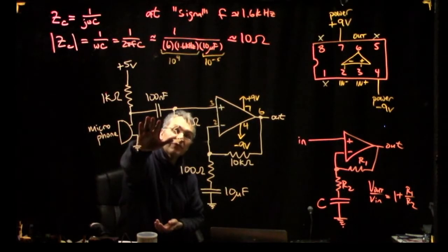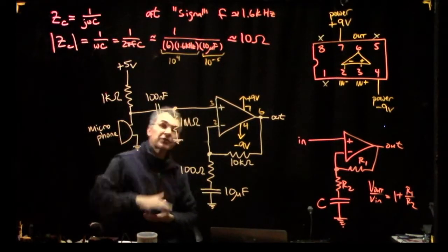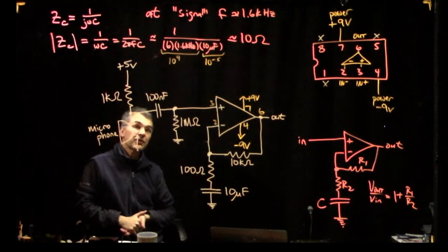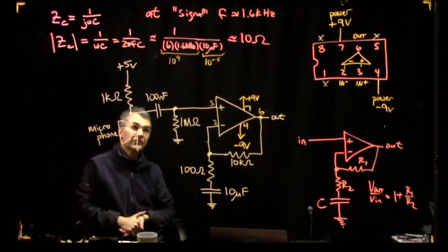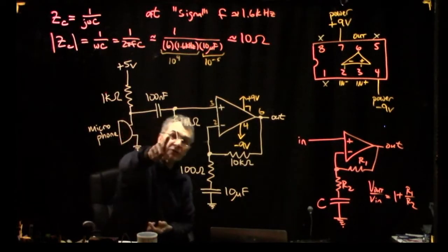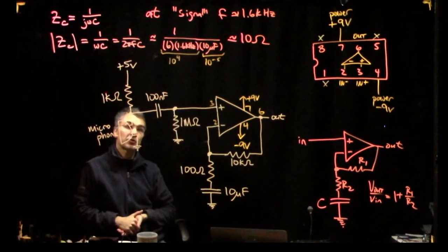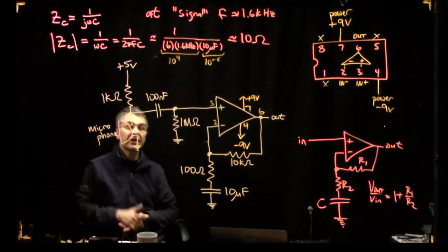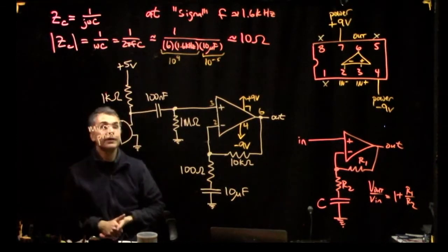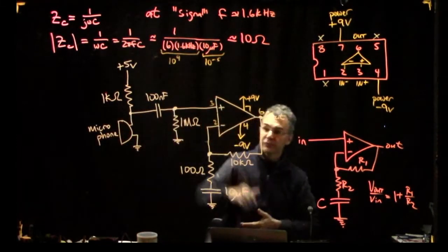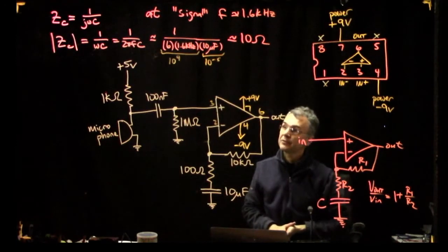This is basically a high-pass filter. You want the high-pass filter to have the longest possible time constant so that it passes even very low frequencies. But there's often a trade-off in electronics: you don't want the resistor so big that the bias current flowing across this resistor gives you a significant voltage here. So a megaohm is a pretty good value.